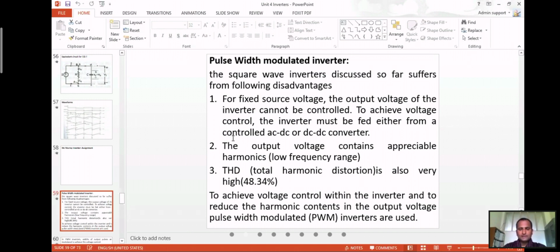Here we have to depend on the duty cycle, the total time period, and the T on time period of that particular switch. So we are using a switch. Switches can be an SCR, a power BJT, a MOSFET, or an IGBT. So how long are we going to switch on these switches, and what is the efficiency of these switches? How frequently can you switch on and off?